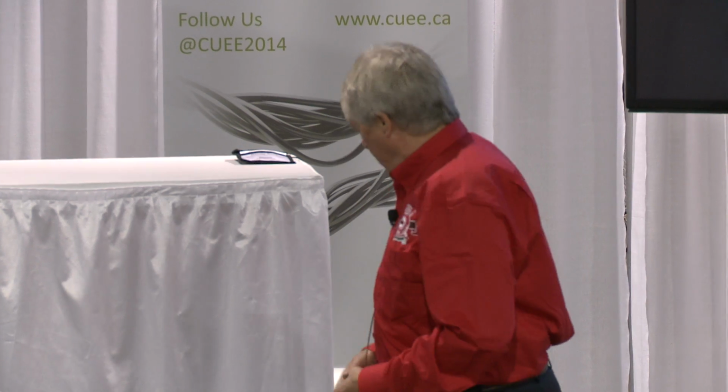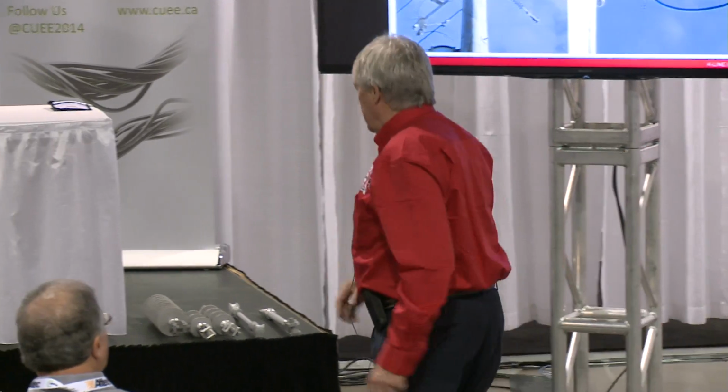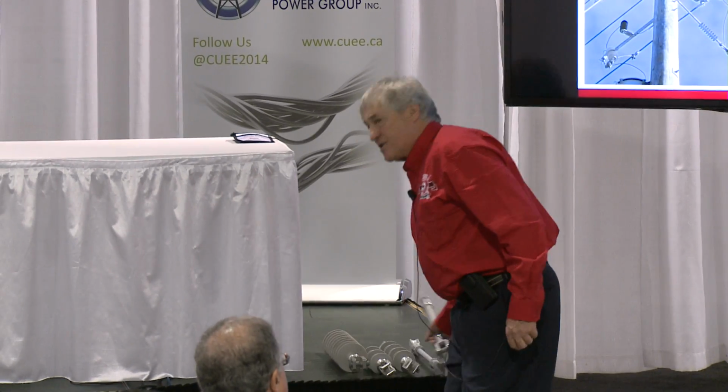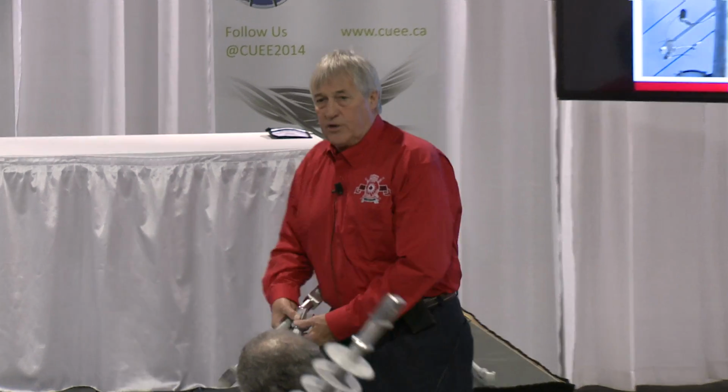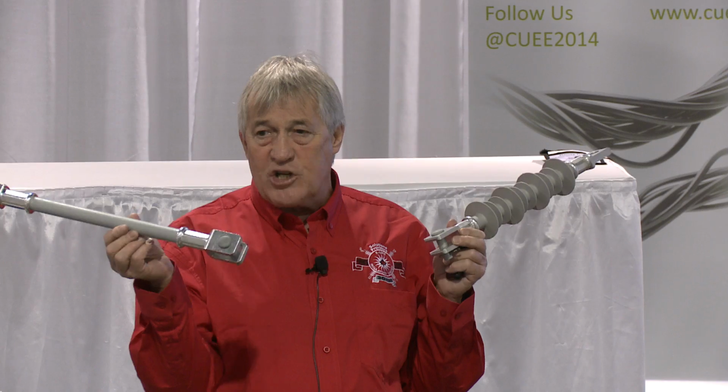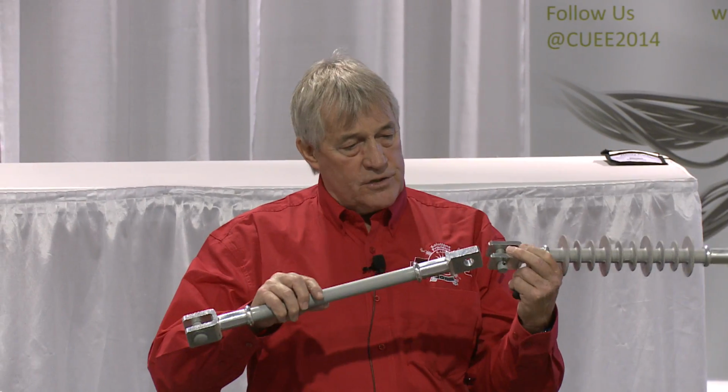We have some customers that prefer the extension insulator. Just pass that around. That's a 15 kV unit. It's very, very lightweight. The 46 is a little bit larger. So we have a lot of customers that like using that. Some clients still prefer, you know, they have certain insulators on standards. They want to use an extension link. So we have an extension link insulator that allows you to do that purpose.